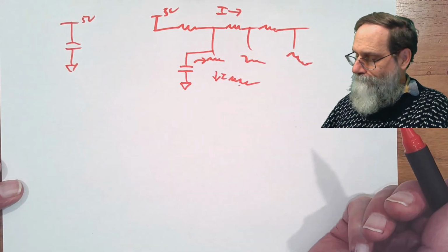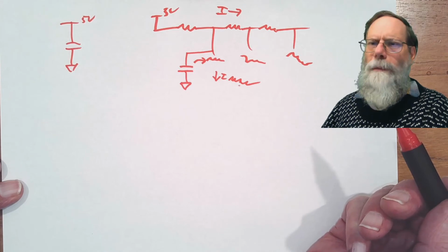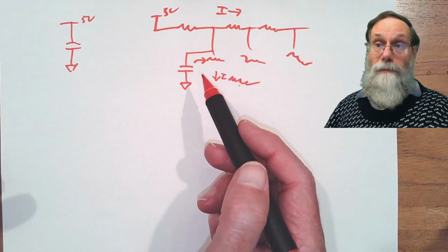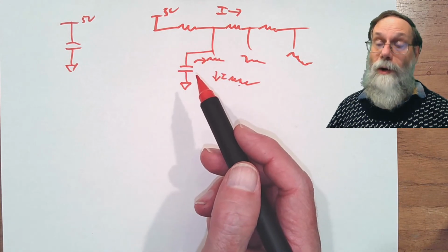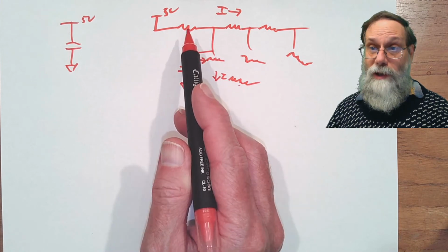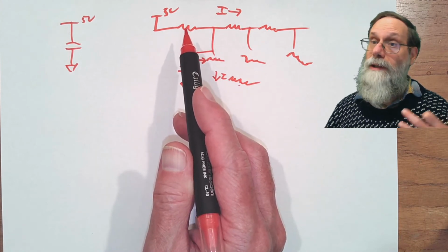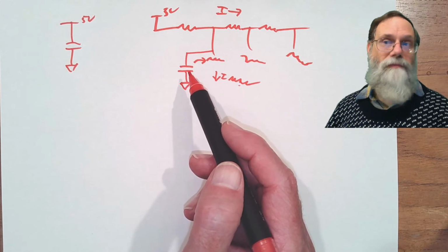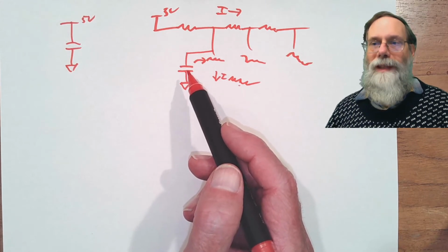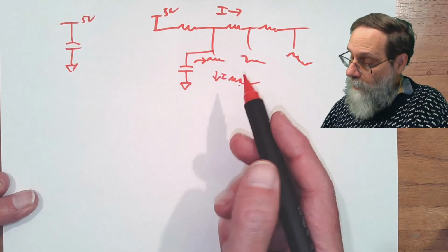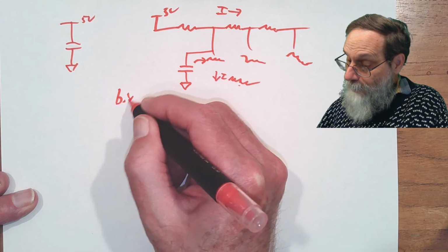Okay, what size capacitor do we use for this? Well, if we're trying to get good reduction in noise, we've got a small resistance here. If we're trying to reduce the noise, maybe we need a large capacitance in order to get a low-pass filter with a low corner frequency. And so you want to use big capacitors.